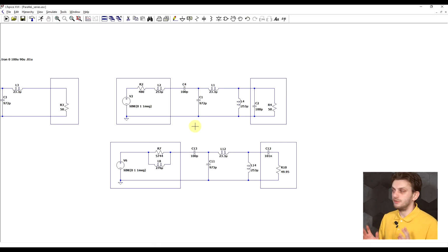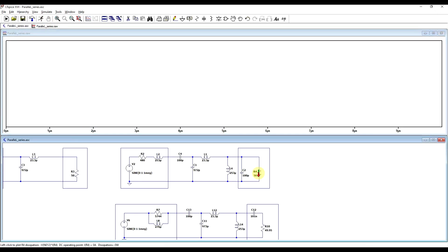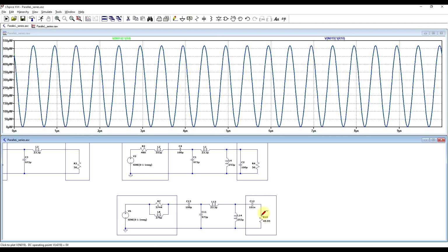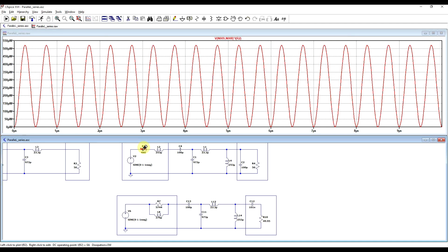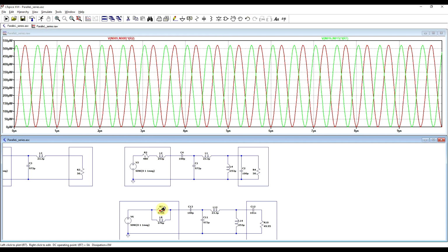Now we can start from our previous circuit and plug in the various equivalents. So for the two series elements, we can put in the parallel elements. For the two parallel elements on the load, put in two series elements. And if we rerun the circuit, just to check that everything's okay, we can see that exactly the same power gets delivered to the load. And similarly, if we look at the source power dissipation, on the signal side in the upper circuit and in the lower circuit, again the same amount of power gets dissipated. So the two circuits are equivalent.